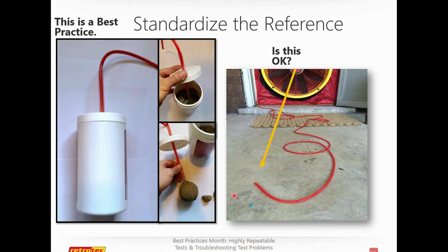If you're in a brick house, I have actually done a test where we're testing the pressure in a combustion safety zone in a basement that is mostly subgrade of a brick house. And on a windy day, we can get a positive pressure on the windward side and a negative pressure on the leeward side. I messed that up.